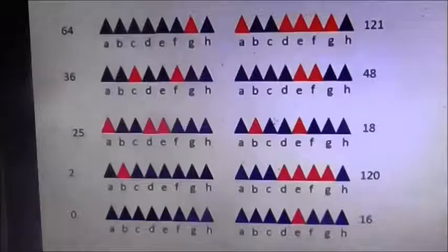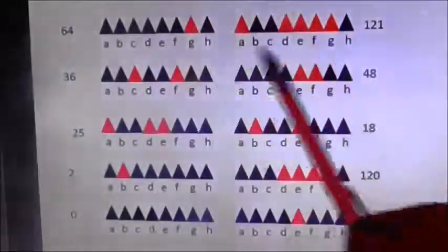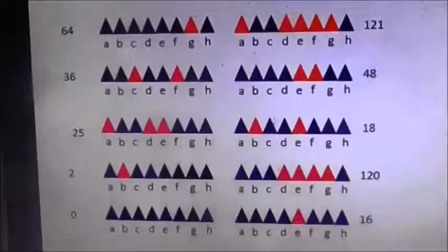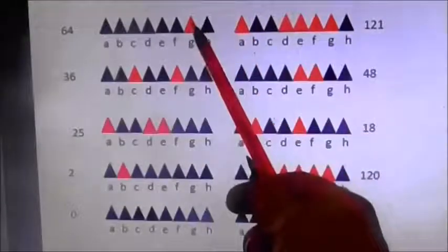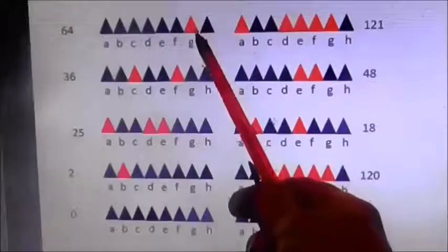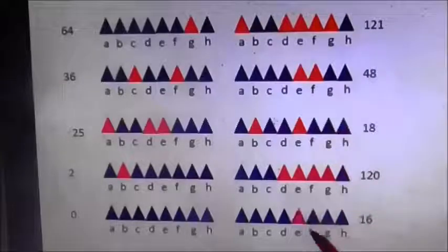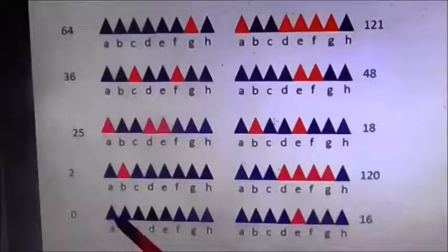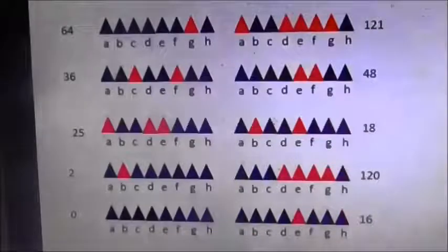And this is the basic idea of how it's done, and these represent the display digits 0, 1, 2, 3, 4, 5, 6, 7, 8, 9. So what we want is every bar that we don't want to shine, we need to make high. And here in 0 we don't want bar G, which is the middle bar, to shine, so we make that high. And here in 9 we don't want bar E, which is the bottom left, to shine, so we make that high. Similarly, this is the display number 8, and we want all the segments to shine in there, so we don't bother making any high, and all will shine.